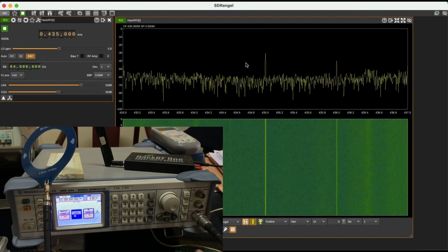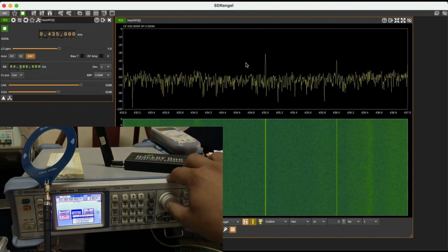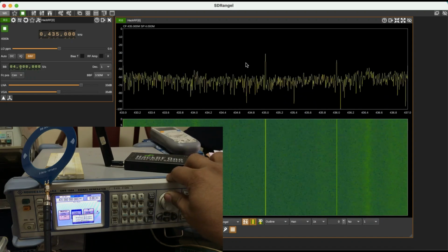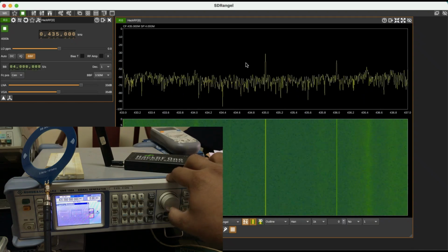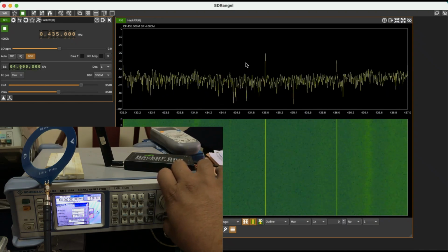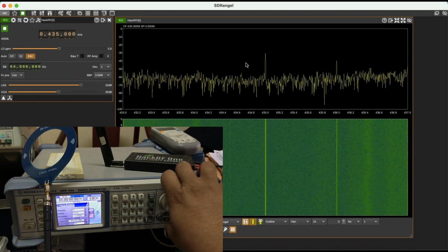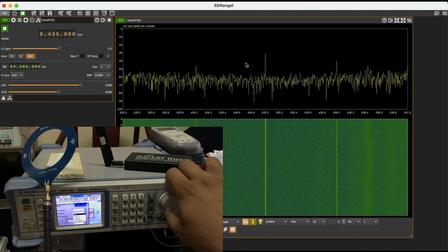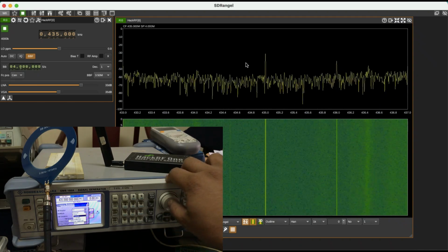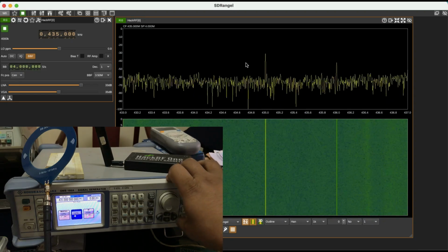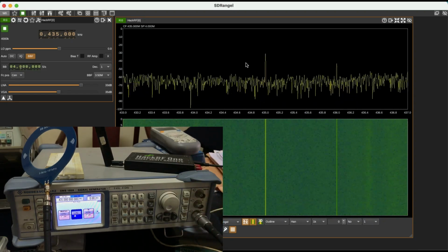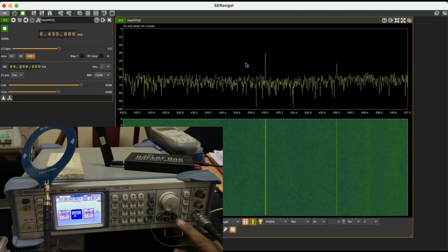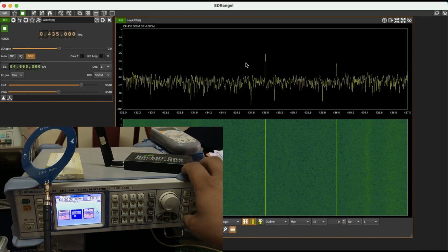Turn RF off, go to my modulation block, and let's go to frequency. Instead of choosing internal source to be sinusoidal wave, let's generate FSK. Just change this to square wave. So let me just go ahead and choose this to be square wave. Escape out of it. So it's still FM, but your information signal, instead of having a sinusoidal signal, now is a digital signal. So I can just simply go here and turn this on.